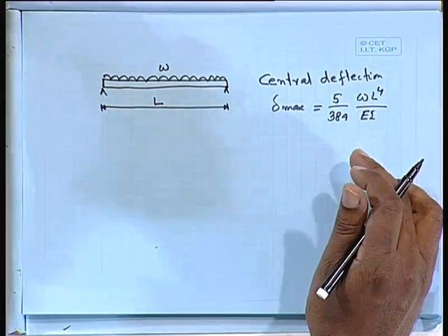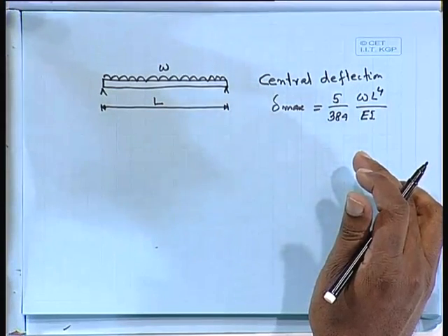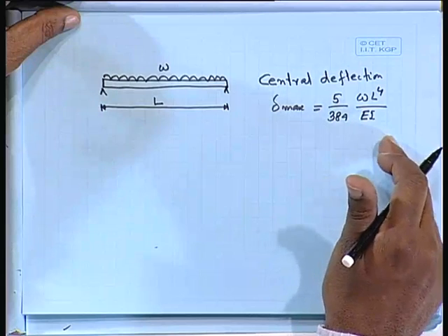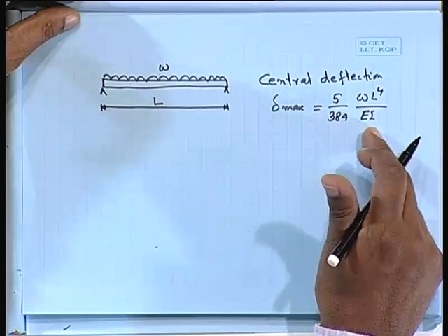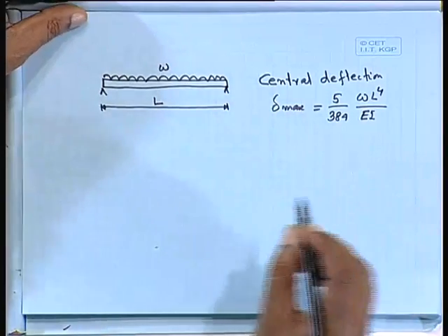So far we have designed for the cracked section. That means only the compression part is uncracked, but at the bottom, wherever we have reinforcement, cracks may appear. So what is the value of E and what is the value of I? That is the major difficulty here. The formula looks very simple, but providing the proper value of E and I matters, because the result differs significantly if we cannot provide E and I. So let us find out.